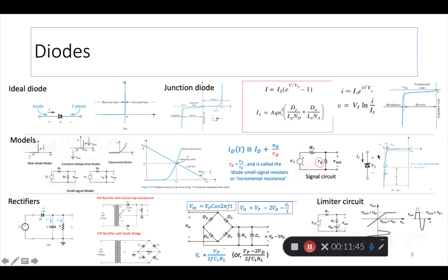One of the big reasons why we work like this, I mean, any diode can be used like this, but a Zener diode is specially designed to work like this, and its big benefit or its big application even today is in voltage regulation. So what that means is, even if the current changes through the diode circuit very highly, all the way from there to there, you see that the voltage really doesn't change much, right? So the voltage is almost constant.